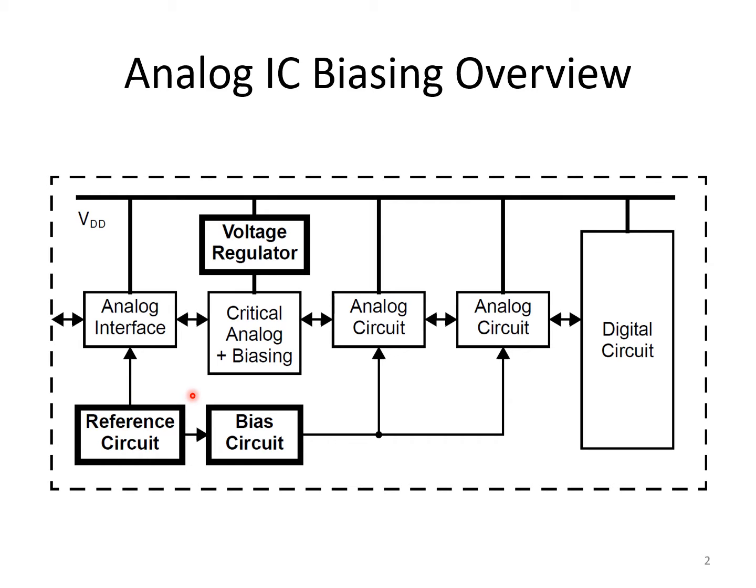within a pretty tight tolerance, whereas a bias circuit is relied upon more to provide a certain amount of current that will keep certain transistors biased in active mode or in triode or to meet a certain performance requirement and so on. So because a reference circuit provides an absolute value constant, it's usually associated with interface circuits that have to deal with the outside world.